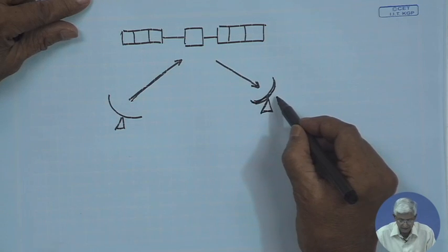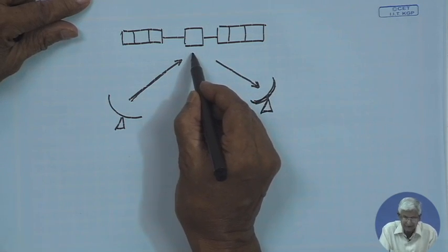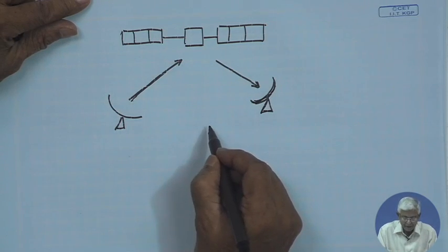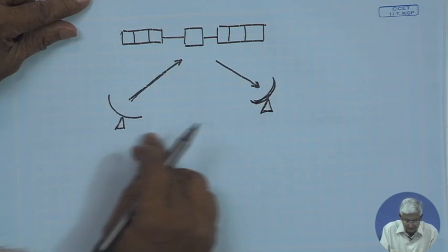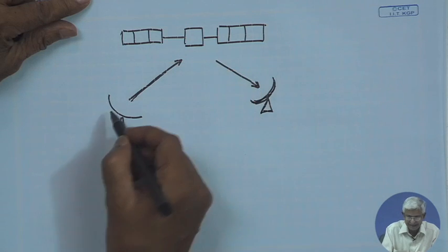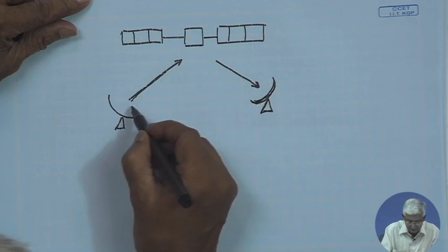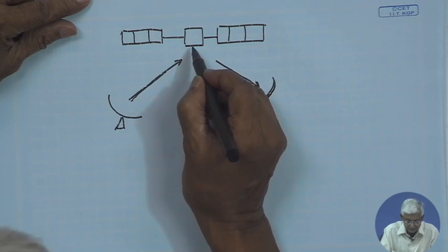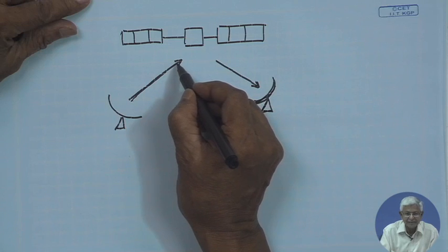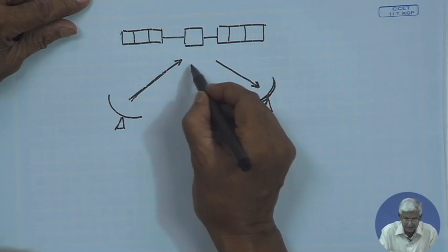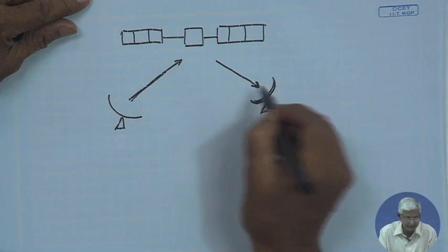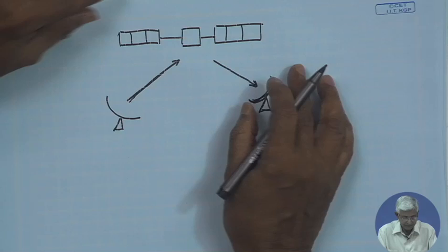But the satellite antenna, whether it is transmit or receive, is pointing to the center of the service area, and from the center of the service area, the transmitting and receiving stations may be a few degrees away looking from the satellite. So, the gain of the satellite antenna towards the uplink station is reduced from the maximum gain by the angle theta, and a similar thing applies towards the receiving station in the downlink. So, those things we will bring into the picture.